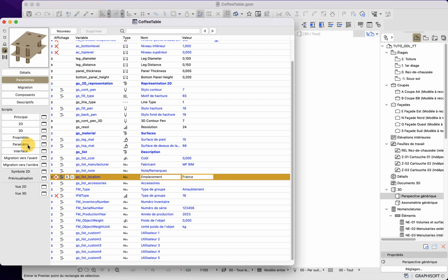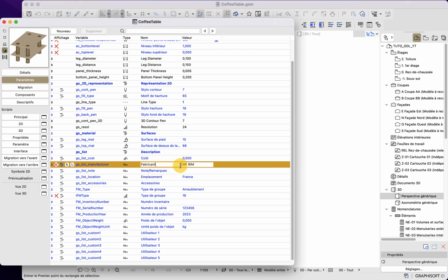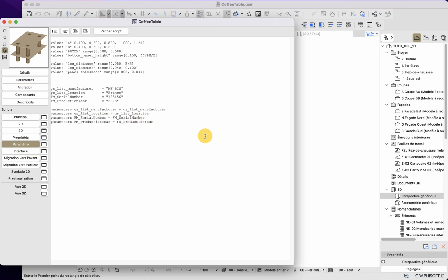So here I can eventually lock those parameters, so I do not tempt the user to be able to change them in a context where it cannot be changed. So here, because I cannot change this, I will lock those parameters. In order to lock parameters, you need to introduce another command, which is lock. Lock expects some text parameter, which is the name of the parameter that you want to lock. So here I want to lock this one, for example.